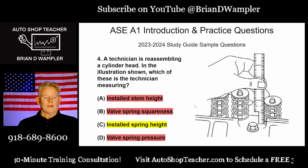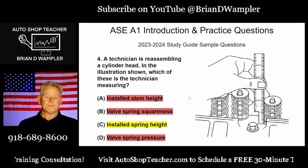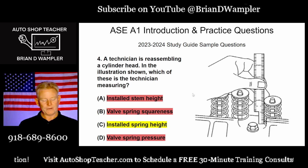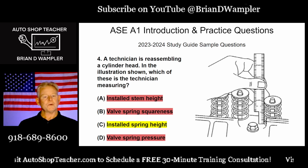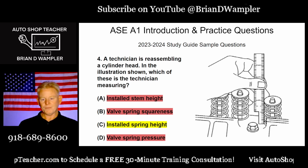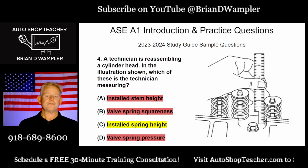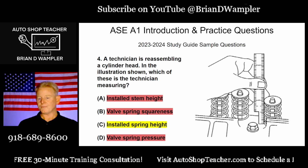Okay? So our answer through process of elimination is this technician is measuring the installed spring height. There's a number of ways that can be done. The one being illustrated here by ASE, in my opinion, is one of the least accurate. But really the amount of accuracy needed would depend upon the type of engine and what type of valve train is going to be operating these valves. Are they going to be a traditional rocker arm with a push rod? And if so, are the rocker arms adjustable?